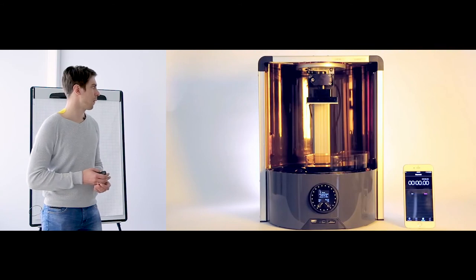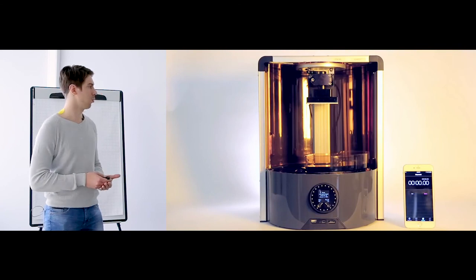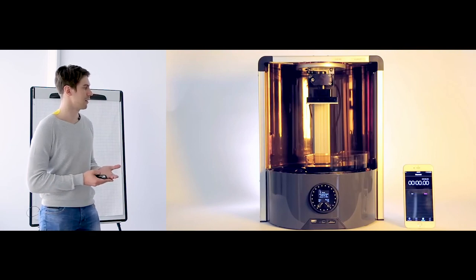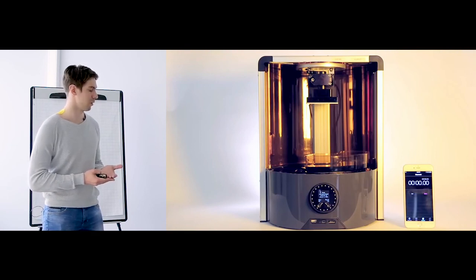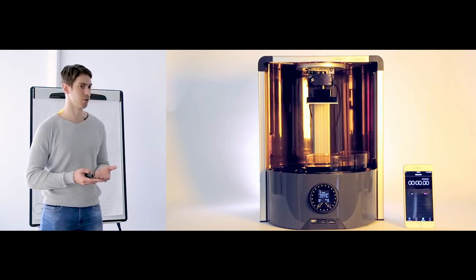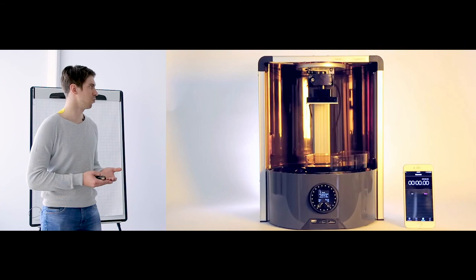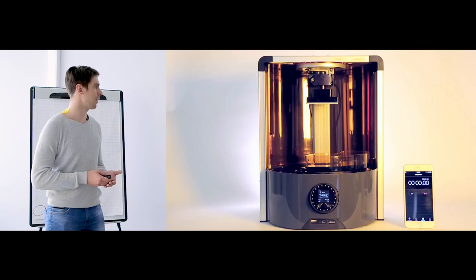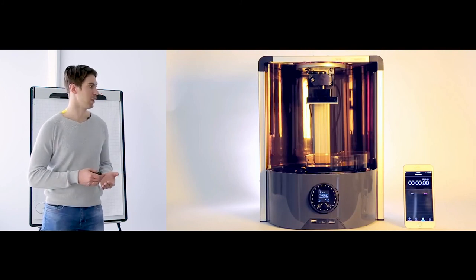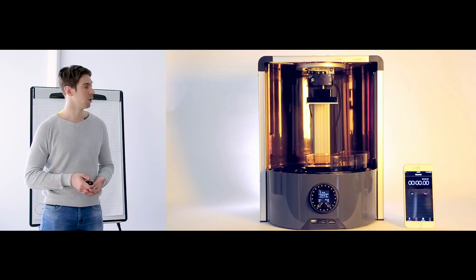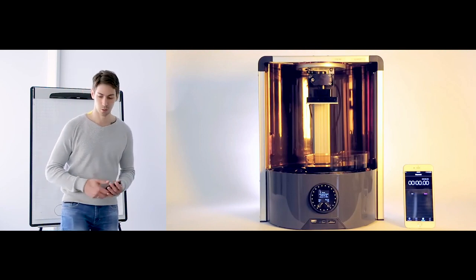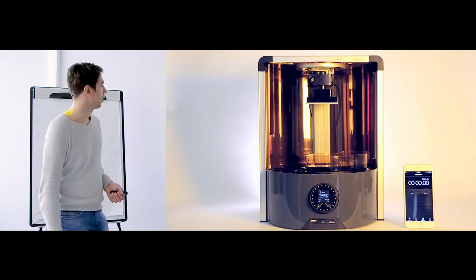While after that, by combining a few factors, one is the big layer height, which enables the possibility to get a layer as thick as 250 microns, which is enough to reduce the suction forces. The other is the choice of geometry, which is not planar and also very thin. All this together enables this printer to work the way a continuous DLP printer works, and to increase the printing speed 20 times. So let's discuss it a little bit more.